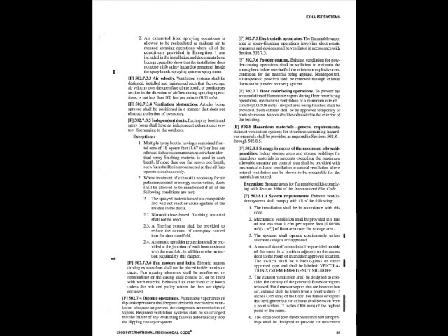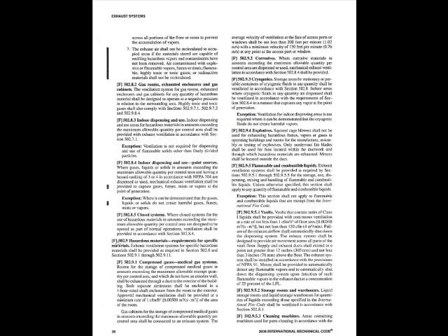You'll notice as we go through it, every single new section of code builds upon it. So for example, when we talk about dipping operations, we're in 502.7.4. Okay, then we have 502.7.5. Then we move to a new main section, 502.8. We're going to talk about hazardous material and the exhaust having to do with hazardous materials. Then we have hazardous material required for specific materials. Okay, for example, compressed gases, medical gas systems, corrosives, cryogenics, explosives. All hazardous materials, but they have specific code for these applications.